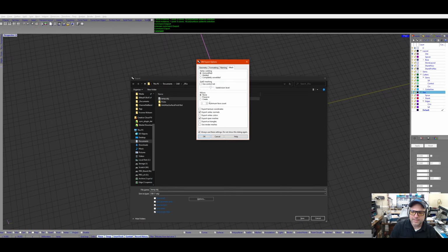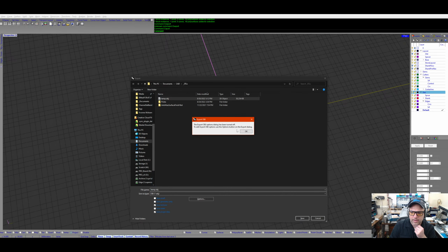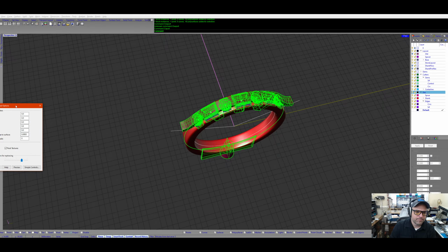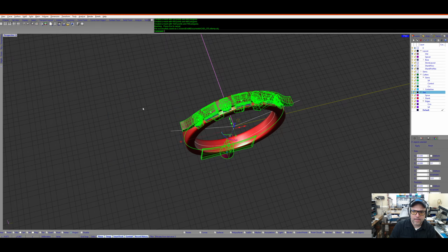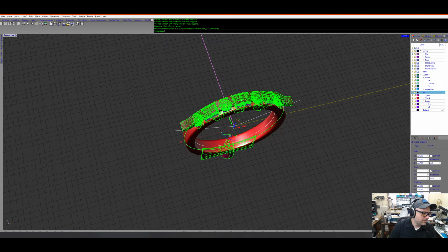Vertex welding. I think the default is unmodified, which we'll go ahead and do, the unmodified version. So this has now been turned off. If you want to see it again, you have to click this button. Okay. We're going to export it. We're going to replace that file. Here it's asking what our mesh settings are. These are the same settings that I had in my little export button. That 0.003 is going to give us a really big mesh. I tell it okay, and then it writes the file.